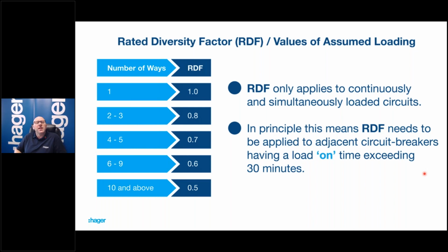And you'll see that these numbers, which are taken from the product standard, are the rated diversity factors. So just like you guys apply diversity when you're designing cable sizes, because if we didn't apply diversity, we would have to have massive cables and massive switchgear to be able to deal with the connected loads. We need to use diversity. So we do it the same as manufacturers.